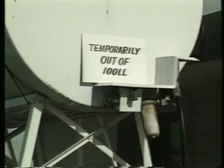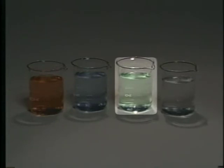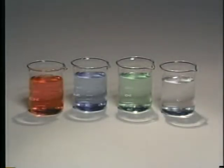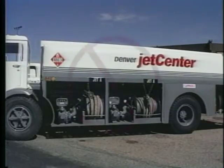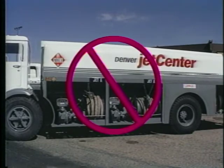If the proper fuel is not available, using the next higher grade of fuel for a short period of time is not considered harmful, as long as the manufacturer has authorized it. However, you should never use a lower grade because it can produce excessively high engine temperatures and cause serious engine damage. In addition, you should never use turbine or jet fuel in a reciprocating engine.